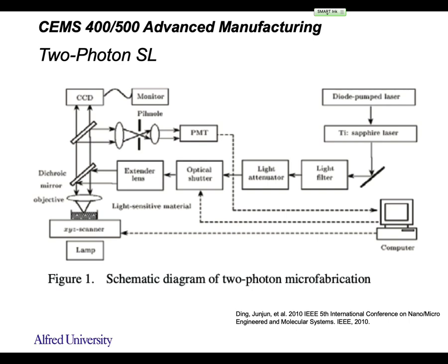So anyway, you get this femtosecond laser, right? You have to modify this laser. You have to use a pinhole to make it a Gaussian beam, right? And you have a shutter to control the on and off of the laser. So this is the lens that can reflect light in this way and also pass the light into the monitor. So then you have a way to monitor your process.